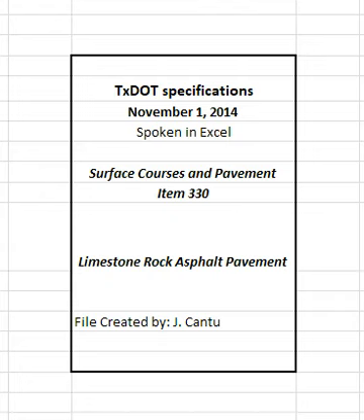4.5 Compaction. Furnish the type, size, and number of rollers required for compaction, as approved. Furnish at least one medium pneumatic tire roller, minimum 12-ton weight. Use TEX 207F, Part 4, to establish rolling patterns that achieve maximum compaction.